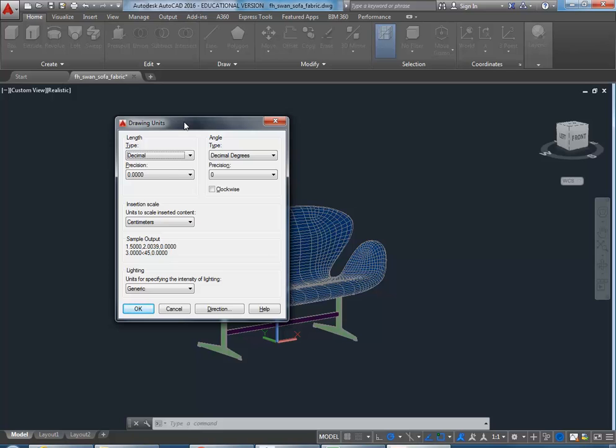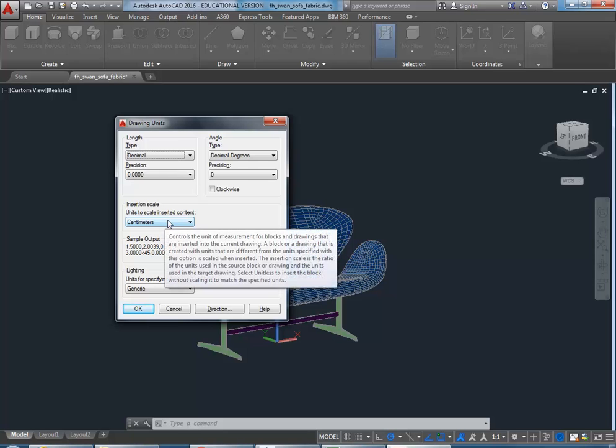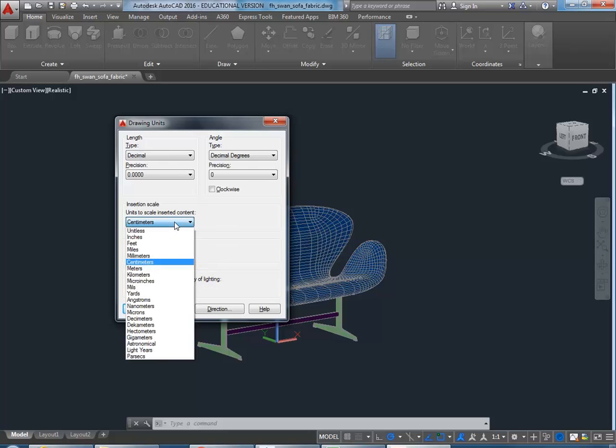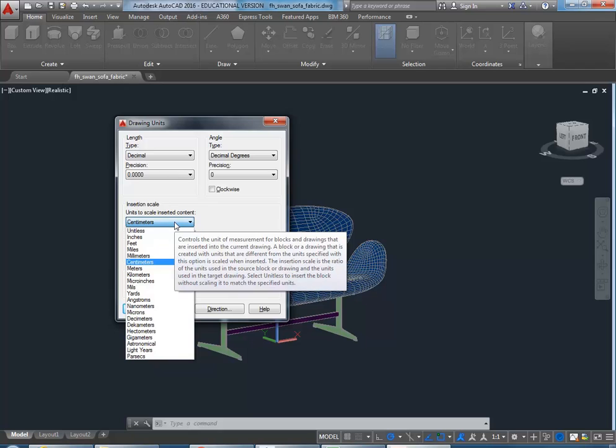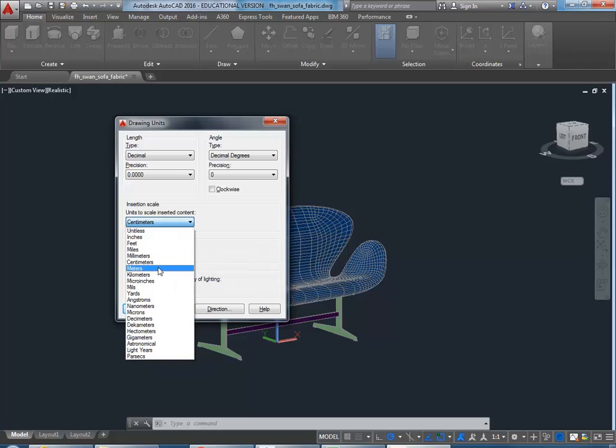So rather than restating the file, like say you're in InDesign, you can just override the unit that they've set and measure it. Well, kind of, yeah. So you can say, I want to be working in millimetres, not inches, but that means we need to change the size of this. There are a couple of ways of doing that. So here, this insertion scale means anything I insert into this file will get scaled according to these units.